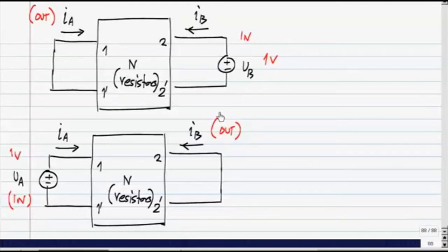Now, you can think of these two circuits, and to avoid confusion, let me put hats on this. It is the same network N, but it is not the same IA and IB that is flowing there, we do not know that. So, I have to put hats on these things. Now I apply Tellegen's theorem to this whole circuit and then see what comes out. Please do that.